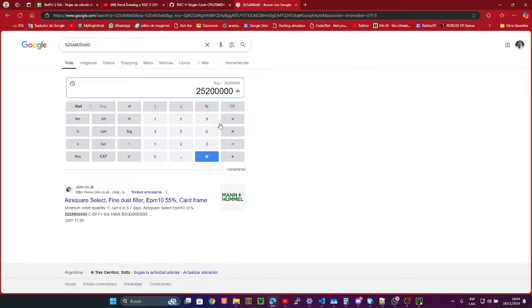The standard VGA pixel clock is not 25.2 megahertz, it's 25.175 megahertz. So it is not actually 60 FPS, it's 59.93 FPS because America's television system is fucking stupid.